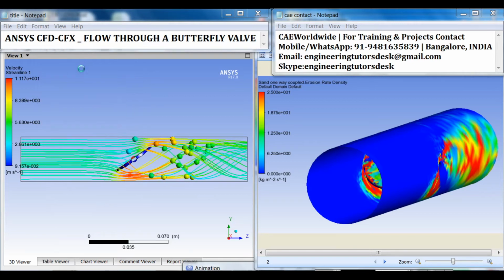Computational fluid dynamics, CFD, is a branch of fluid mechanics, and a computer-based tool for simulating the behavior of systems involving fluid flow, heat transfer, and other related physical processes. It works by solving the equations of fluid flow in a special form over a region of interest, with specified, known conditions on the boundary of that region.